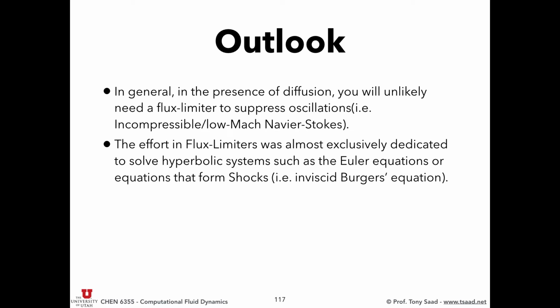Now, the effort in developing flux limiters almost exclusively focused on compressible high-speed flows, specifically the Euler equations. Euler equations are inviscid compressible flow equations, where there is a propensity to develop shocks, and you want to maintain those shocks and resolve them.